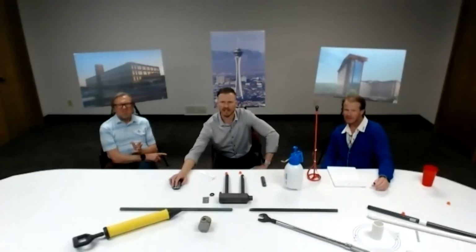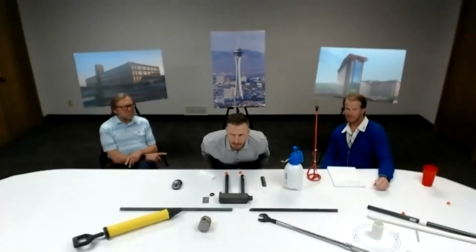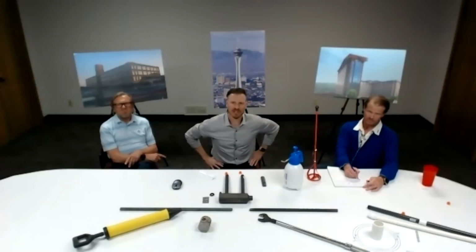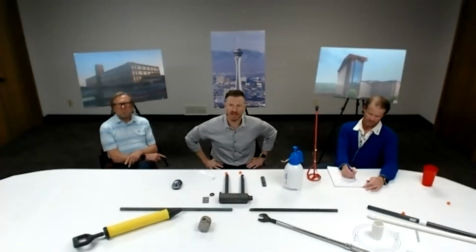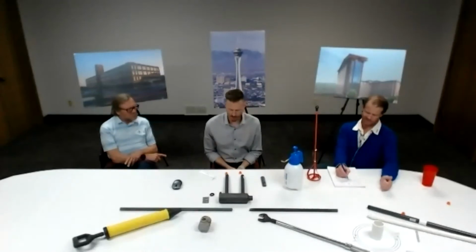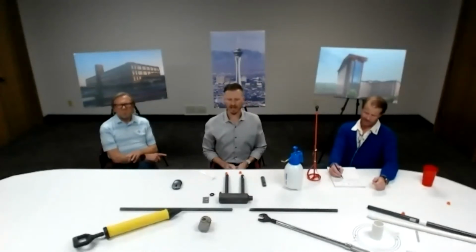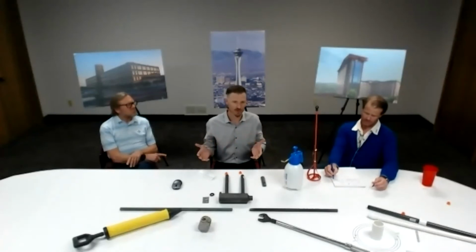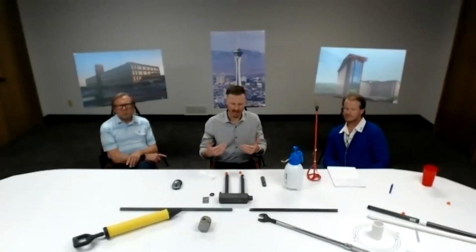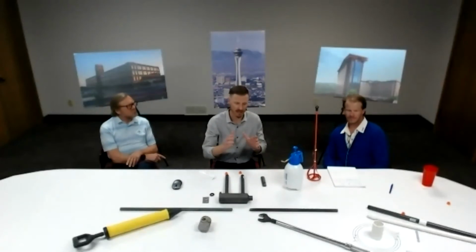Very good question, because this shape comes up about reshoring. The question is, how is the vertical shear transferred through the slab self-weight after forms are stripped and construction joint loading prior to grouting? Right now our position is that you're going to reshore just like you would a traditional pour strip, however the EOR specified. Most of the time we see this at a third point off the columns, or in the middle of the slab at the pour strip itself.